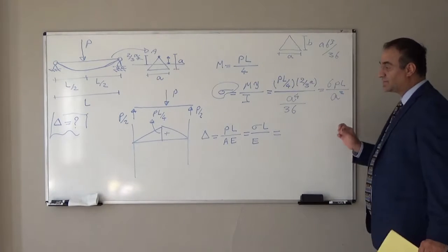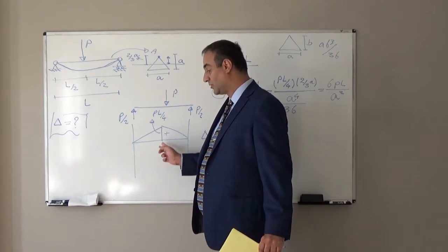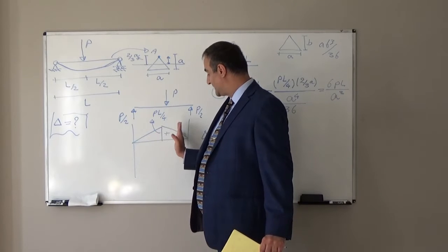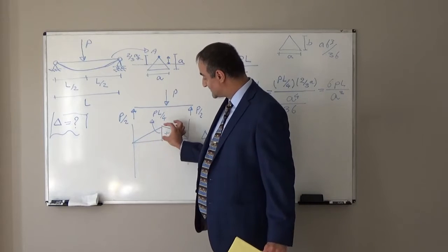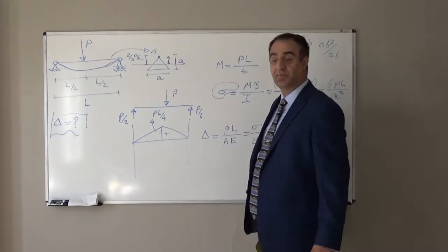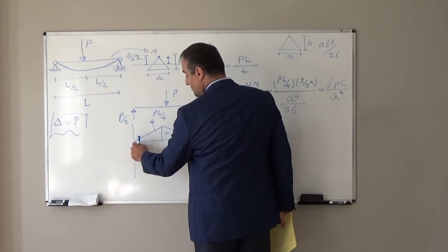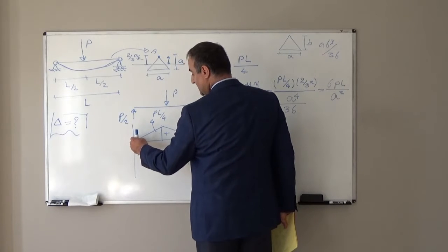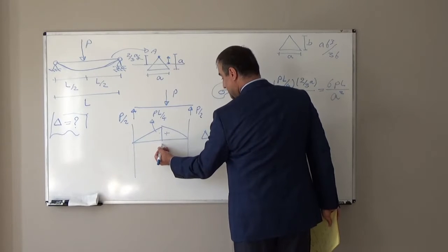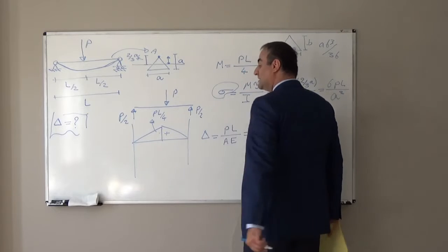But that will take place at the maximum bending moment location at midspan. From the maximum, it reaches zero at the support. So here the moment is zero, so the bending stress is zero. It will increase from support to midspan, and then from midspan to the support again, it will decrease.